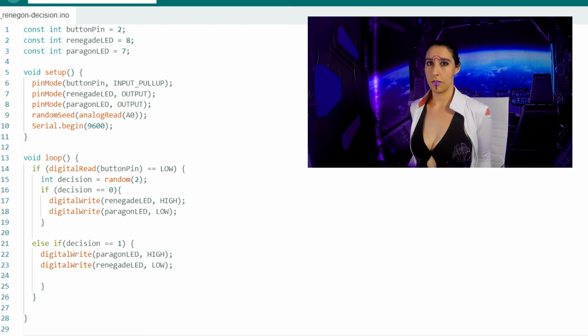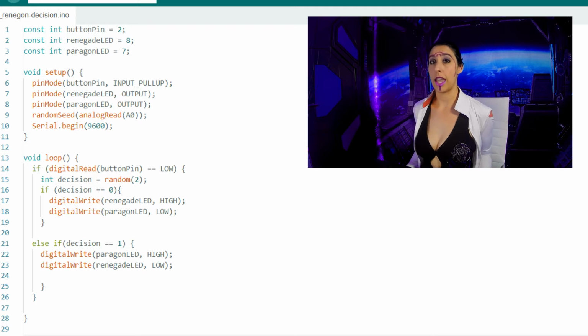When you want the sequence of values generated by the random function to differ on subsequent executions of the sketch, you can use a random input like analog read with an unconnected pin as the argument. The reason this works is because an unconnected pin is in a state called high impedance. It's floating between binary 0 and 1. That gives you a much more random sequence than putting in a fixed number as the random seed.